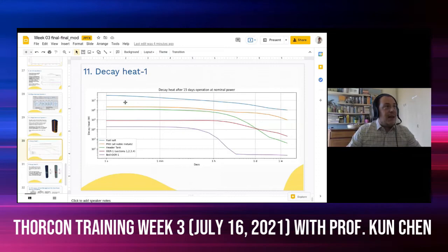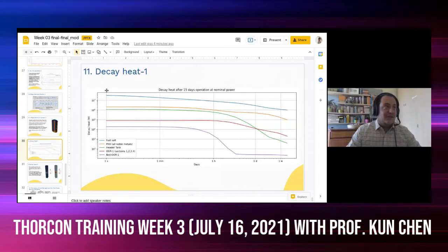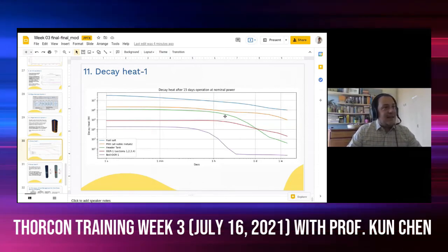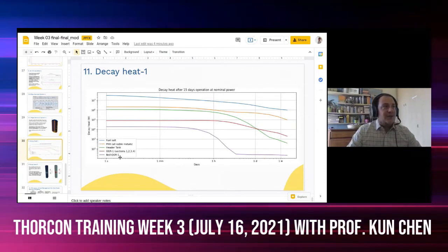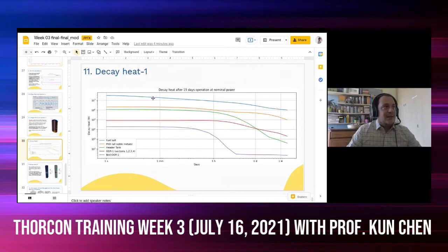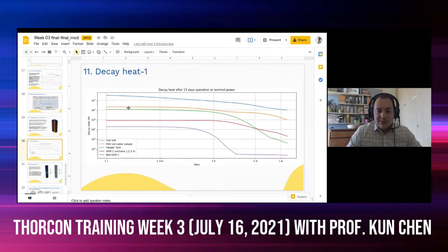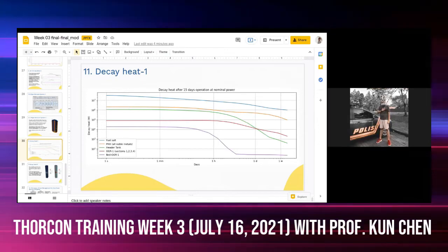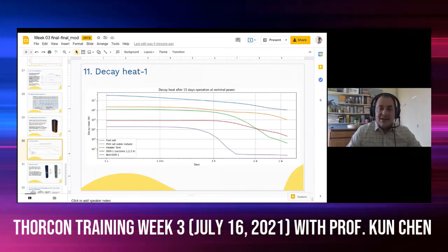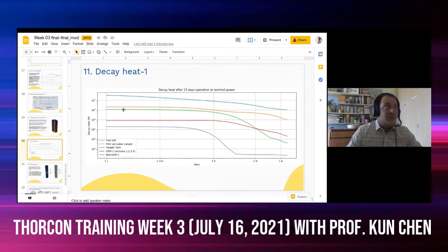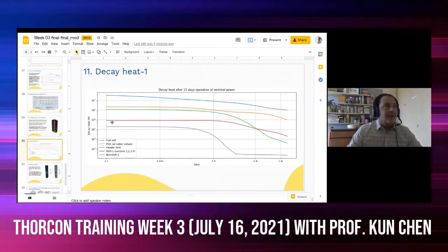But this also implies that the decay heat is not only released inside the fuel. We are analyzing here the distribution of decay heat in the first few days after shutdown: in the fuel salt, in the cold trap or primary heat exchanger, where the noble metals, or let's say the insoluble fission products, might plate out, the header tank, as we were seeing before, and the first OGR.